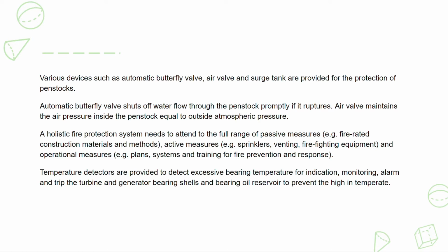So yeah, followed by temperature detectors are also being provided to detect excessive bearing temperature, with indication, monitoring, alarm, and trip of the turbine and generator bearing shells and bearing oil reservoir to prevent higher temperature. So basically, temperature detectors are to detect the temperature level.